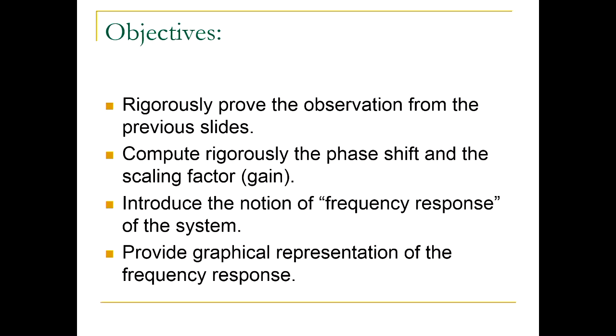The internal model principle allowed us to perhaps track or reject disturbances at a single frequency. If you use these methods, you will be able to deal with disturbances in a range of frequencies, which the internal model principle can't deal with, right? So you can have infinitely many frequencies that you're dealing with, and you're designing a controller that ticks off a box in terms of performance for the range of frequencies, both for tracking and for disturbance rejection. So it's a very powerful set of tools.